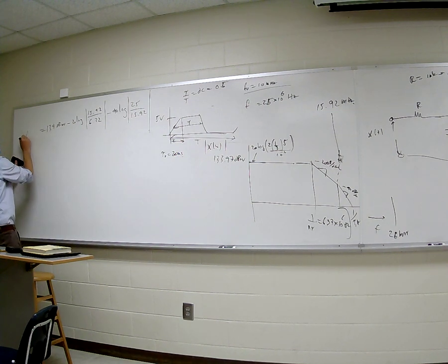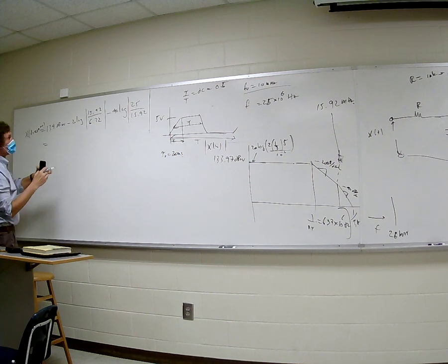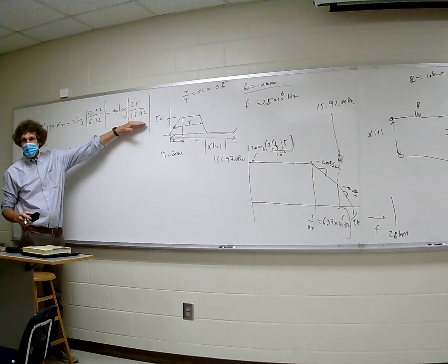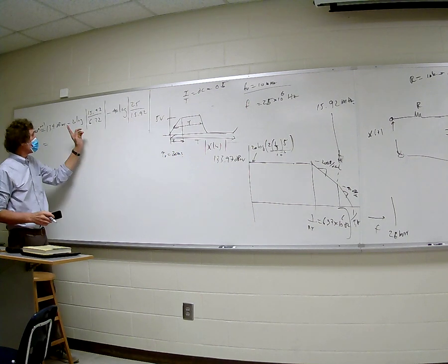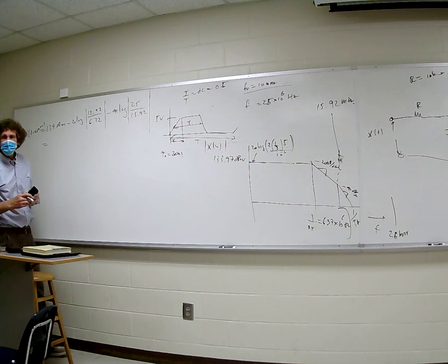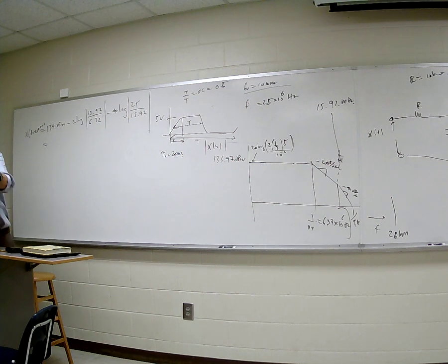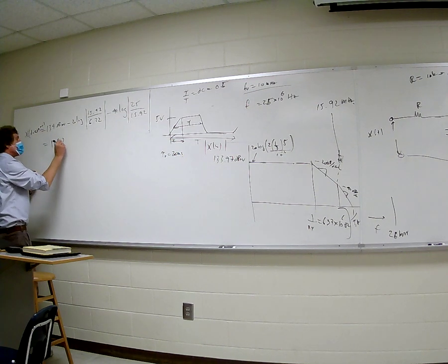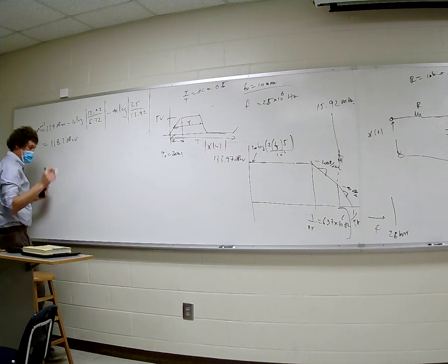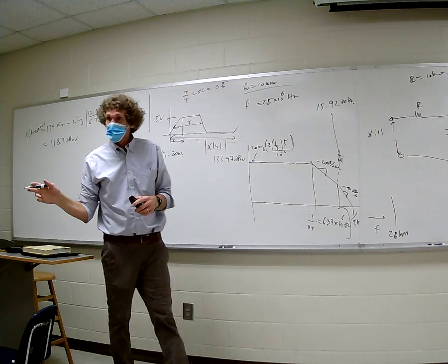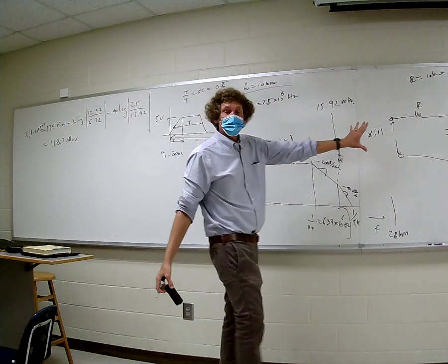So that's going to be the magnitude of X at F equals 25 megahertz. I got 118.2. And you got this value and subtracted this value from it. Yes, and I put the units in there already. And you put a 20 and a 40, right? Yes. Okay, can anybody confirm that? And I subtracted it from 134 already. So what did you get again? 118.2 dB microvolts, right? Mm-hmm. Y'all with me? That's the level of the input signal strength.